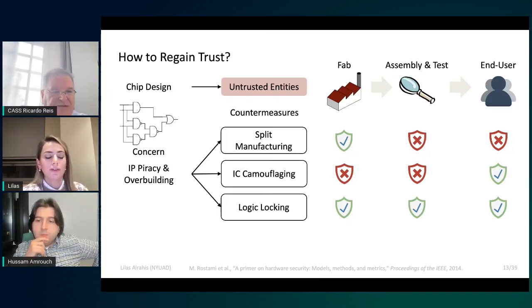Yeah, it is something, of course, we have observed. Logic locking specifically can be implemented at different levels. It can be implemented at the RTL, or at the gate-level netlist. And we can observe two changes. One is when you perform synthesis, which on its own will perform some optimization. And then further, when you do the physical design, you will have some optimization on top.